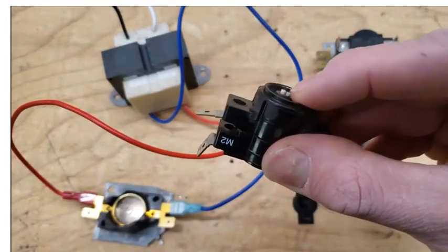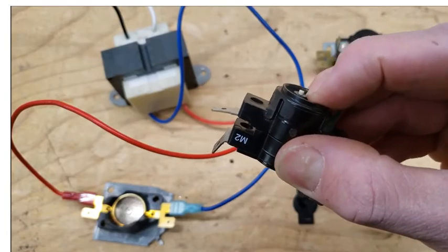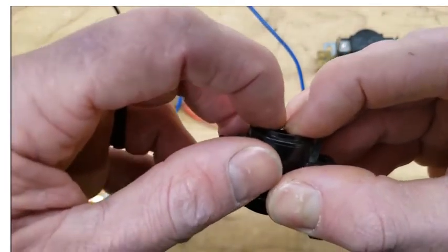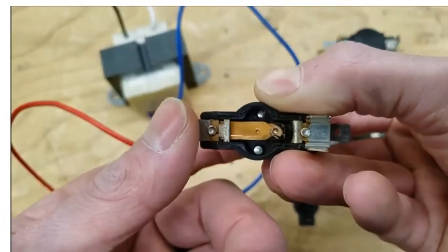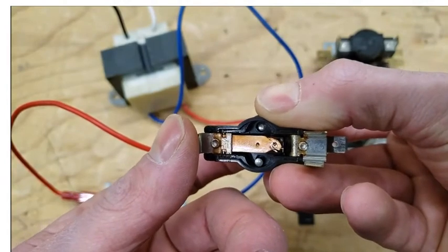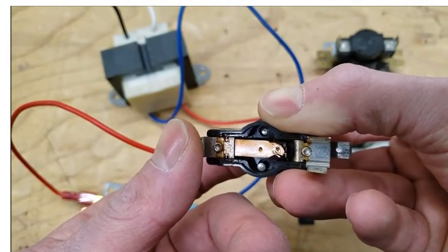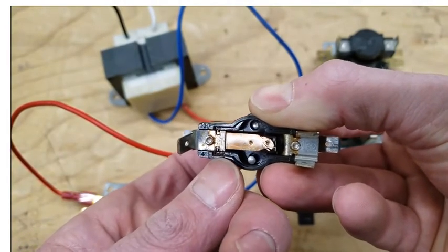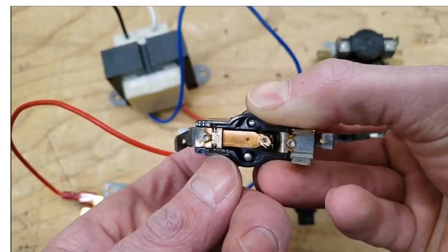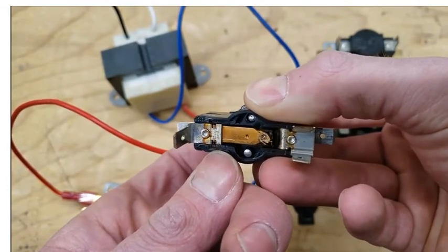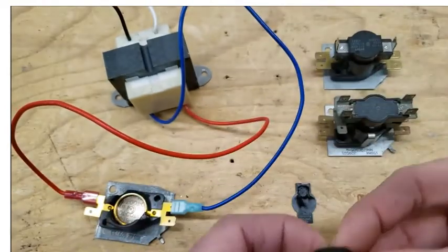So you see you have that second rod in now, and it's normally going to be like this. They're normally both going to be pushed inwards. And so you have the contacts on the top. They're open until you power the sequencer and then wait for the allotted amount of time. Then it's going to close the contacts. So you see how it can open the contacts or close the contacts.